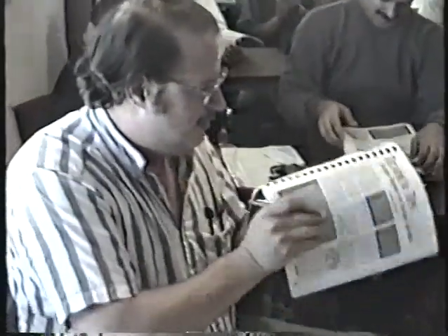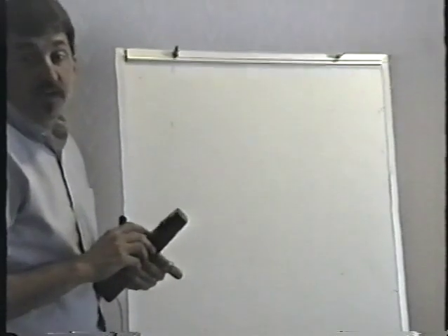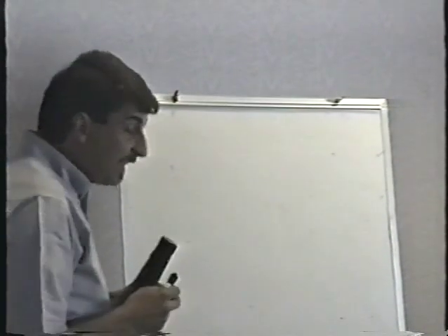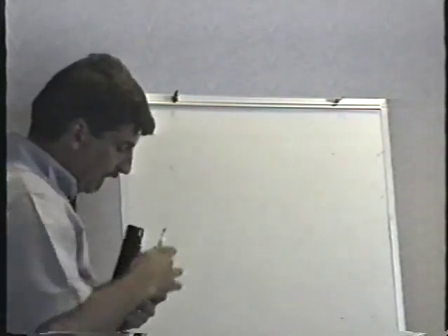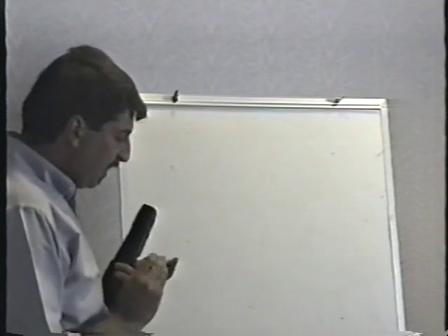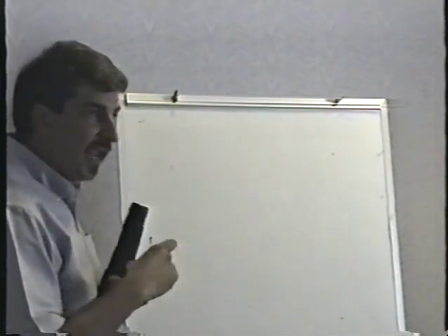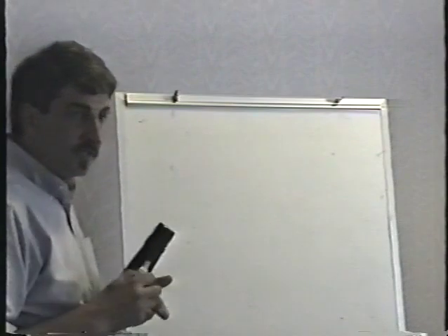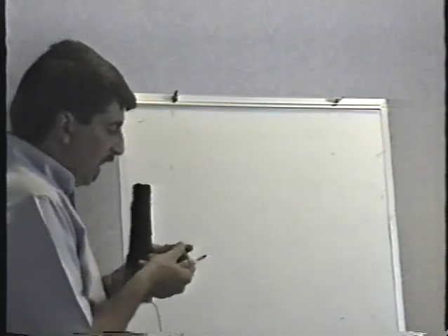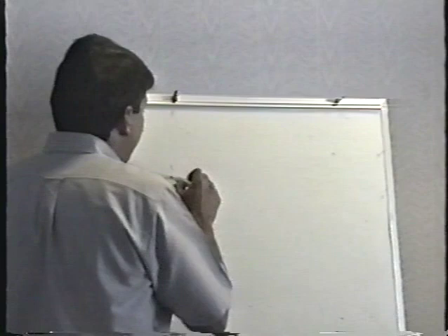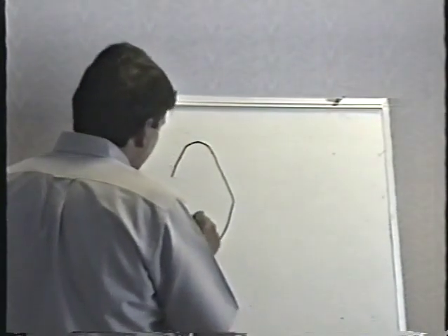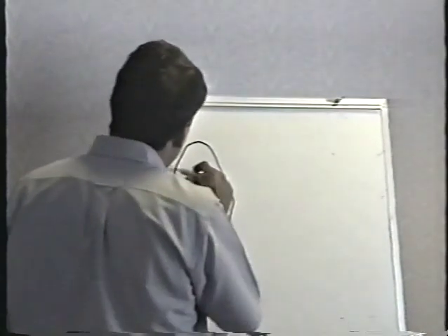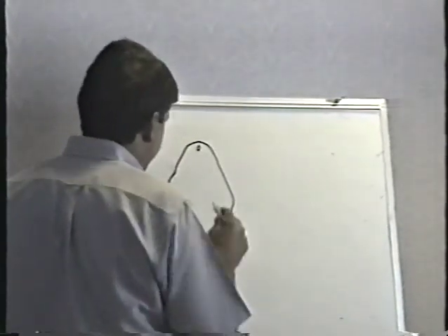Turn in your blue book to page 10. In order to test the transistor, you do have to know which lead is which. You have to know which lead is the emitter, which lead is the base, and which lead is the collector. If you look at the TO3 package that I gave you, that's the big one, the TO3 package, you see that there ain't but two leads sticking out of this thing. In this particular case, they're labeled, but they aren't always labeled in all these transistors.